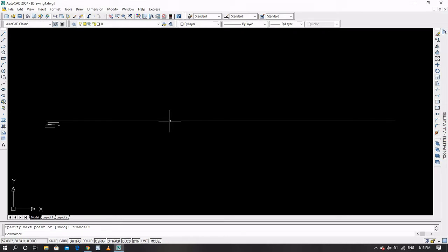If I want to draw 100 feet, with units like meters, centimeters, inches, for that I will set units. So in this video we will learn how to set units. Units are very important in the beginning and at the end. So whenever we open AutoCAD, we will keep in mind that we will set units. For units, I will type UN, its short key, enter.